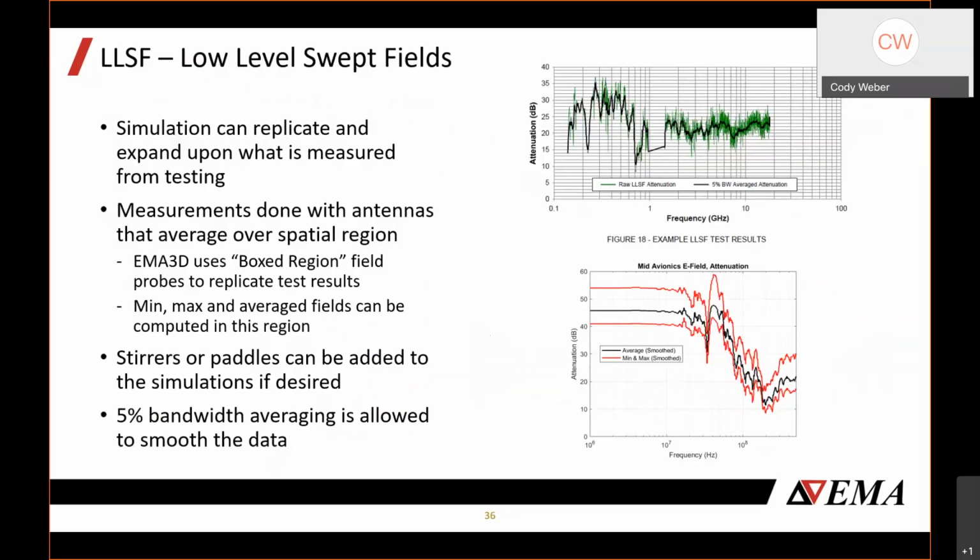So when it comes to LLSF, these ones are a bit trickier to characterize and validate, in my opinion. As with the cable currents, these simulations can replicate and expand upon what is done during testing. But there are some tricks if you're going to be doing a validation or as you process your data to use for verification purposes. When they do these measurements, oftentimes they're done with horn-shaped antennas, and what these do is sort of an averaging of the fields over a spatial region.